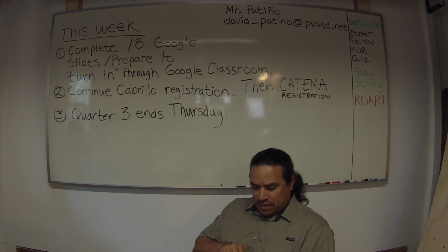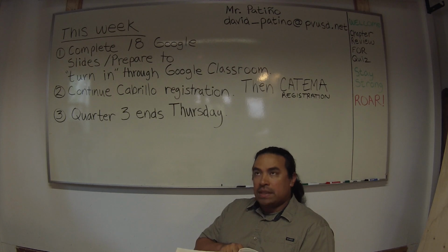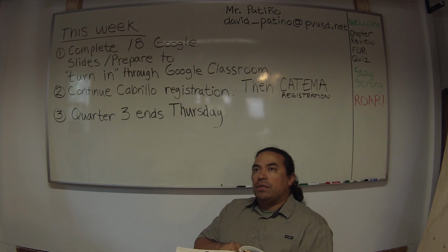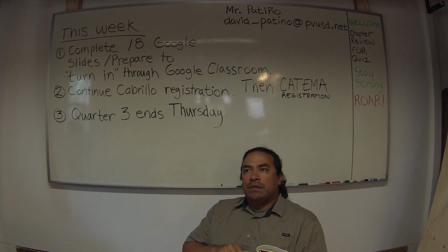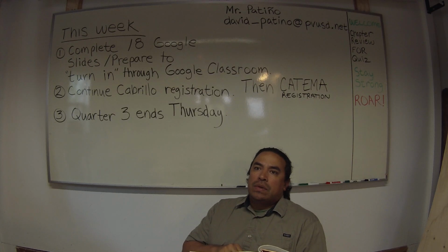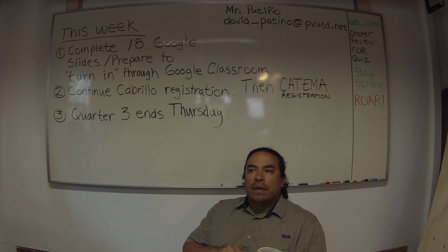Equilibrium and moisture content. Oh, before I go into equilibrium and moisture content, a tool for selecting the correct type of wood, humidity-wise, is actually a humidity sensor. And you can use this to tell if your wood is ready to use. If it exceeds a certain humidity level, you would be best off waiting for that wood to dry more in certain applications, because the wood will twist and warp and may not be stable because it's not completely dry or within that dry range, that 7 to 10%.